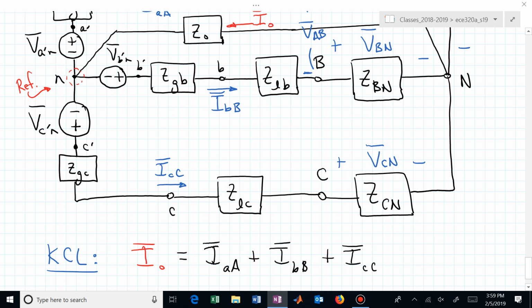Do you see a triangle? So you have I sub A, and if that's the reference, if you've drawn the line in the sand, that's going at 0 degrees. And if this is a positive phase sequence, what's I sub B? That's at minus 120. I'm going to run out of space, but I'm walking a triangle. So I'm going positive, I sub A, then I go minus 120, I sub B, and then I go back.